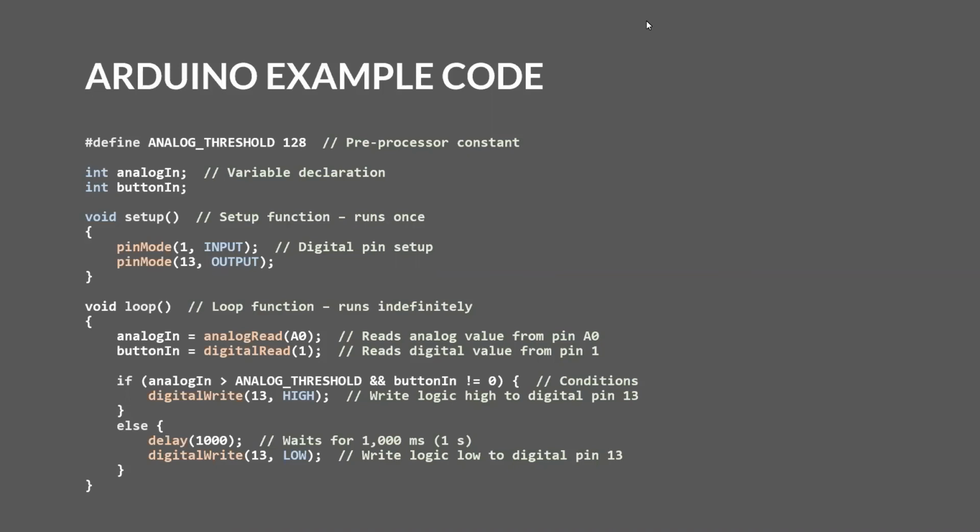So if you've just set up something, in some cases you need to, especially with things like analog components, wait for maybe a few milliseconds for that analog component to sort of stabilize. And in that case, you can use a delay just to stop the CPU from proceeding with the code until that analog component has stabilized and is ready to move on. Any other questions before we move on?